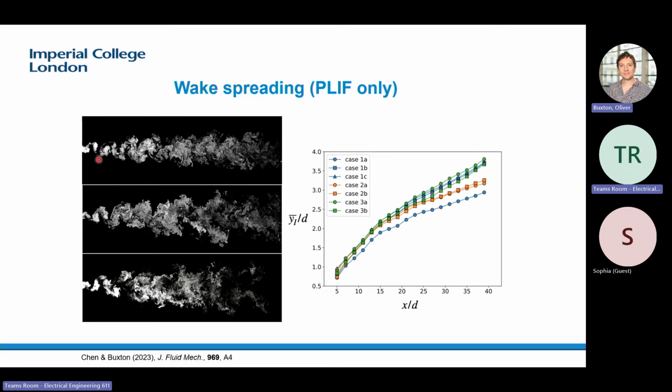to the end. And so if we just look at essentially the average location of the interface, and we plot that as a function of streamwise distance for the different cases of background turbulence we have, we can see that there seems to be fundamentally one slope in the near wake and then a second slope in the far wake. And by and large, this seems to coincide with a location around 15 diameters, which captures the coherent motion within the wake. So again, wind turbines have got this coherent motion in the wake. So clearly these coherent modes are going to be important in determining the entrainment rate at a practically useful distance.